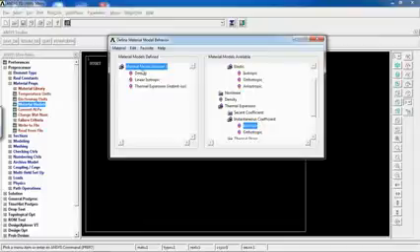So for material model number 1, I have defined density and the mechanical properties in terms of Poisson's ratio and elasticity, and also the instantaneous thermal expansion coefficient. While I was defining all of them, they were recorded for my material model number 1, so it doesn't mean that I have 3 different materials defined in my analysis.